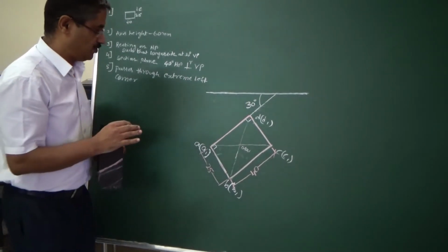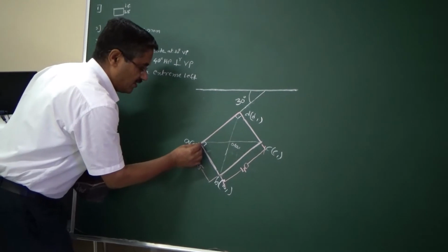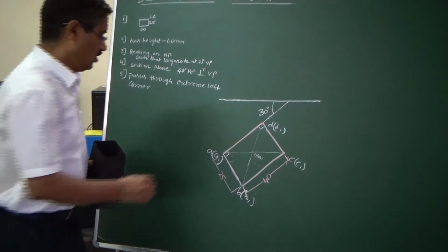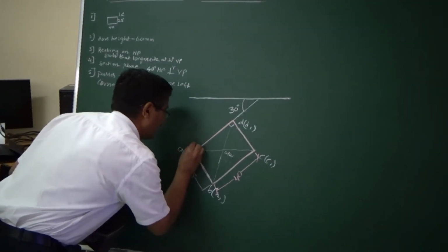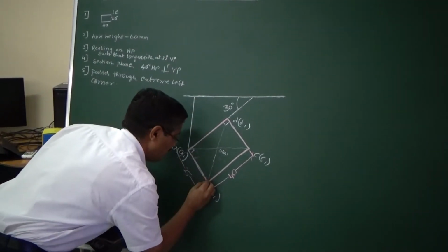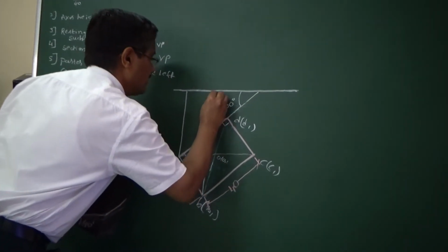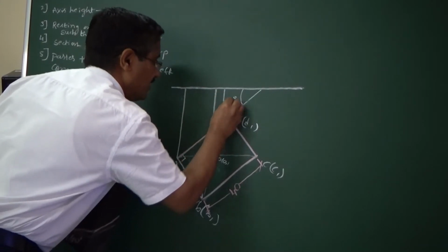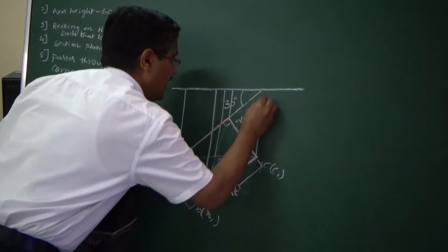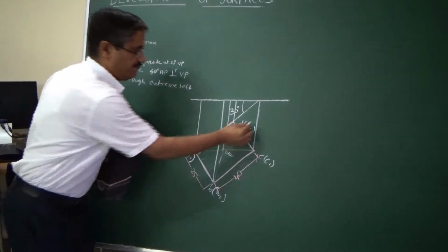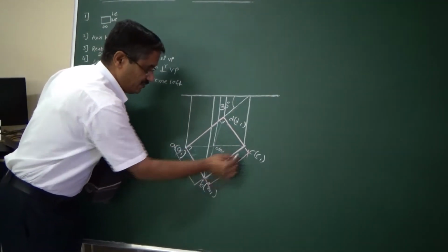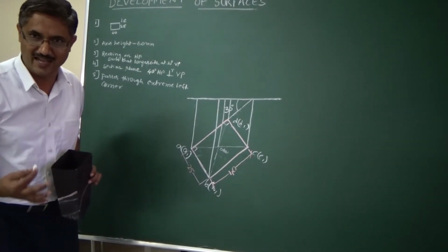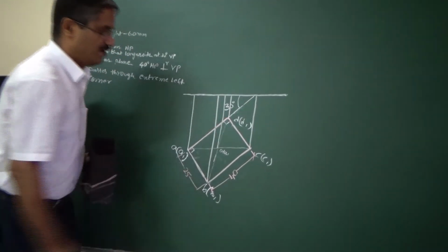After completing the top view representation, as with the solid, you have to project this to the front view. So I will be doing it now. I am drawing the lines from all these points, including the axis line. When you include the axis line, look at this, there are 5 lines here. Why? Because the 4 points are here and one axis line, which is not merging with any other lines now. So you are bound to get 5 lines.